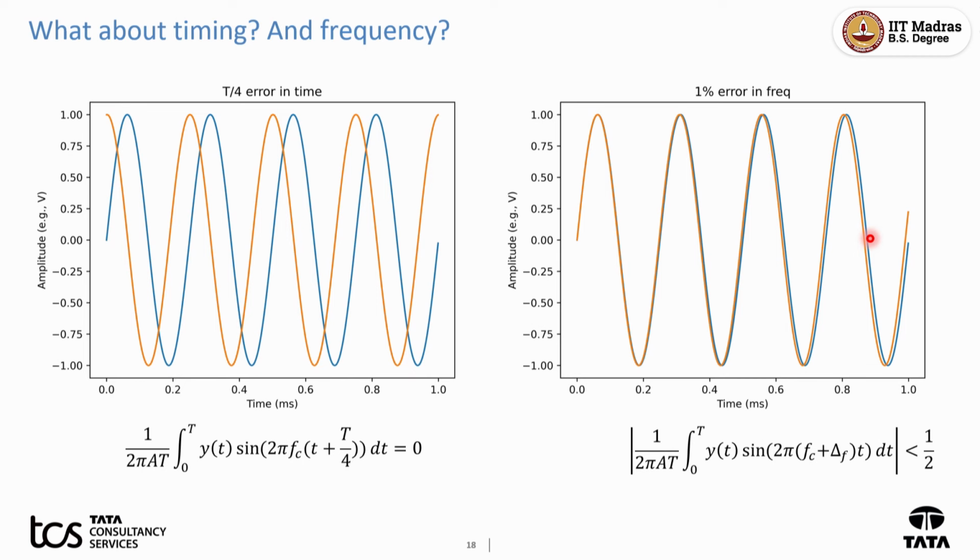Okay? So, you cannot let that happen, because if you happen to be at the point where the cos wave is 0, you will say all signals are not there, correct? So, you have to keep on correcting the frequency errors. The phase errors have to be corrected millisecond by millisecond in 4G and 5G. In 5G, you may have to do it every 0.5 milliseconds. In 4G, all receivers do it every millisecond. Every millisecond, they must correct for frequency. The only thing they are guaranteed is that it won't be so bad that you cannot correct it. It will be plus minus 0.1 for a million hertz.